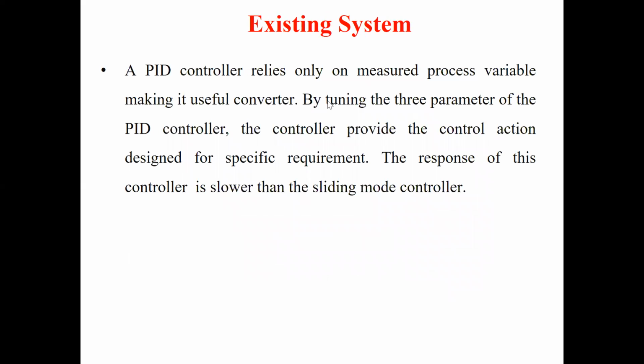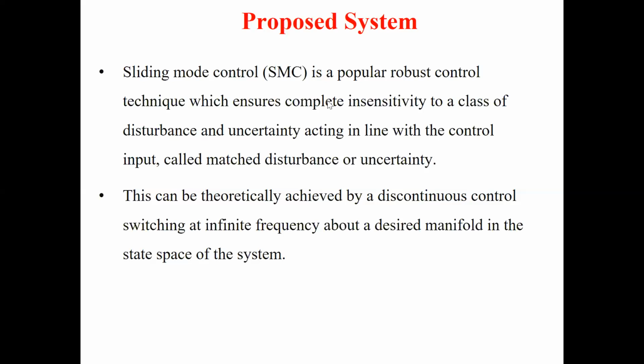They have different controllers, PID controllers, and we use some genetic algorithm or ACO, PSO. A lot of optimization algorithms are there. People used these optimization algorithms to determine the exact value of KP, KI, KD, which are the gains of the PID controller, and then they move forward comparing all those things.